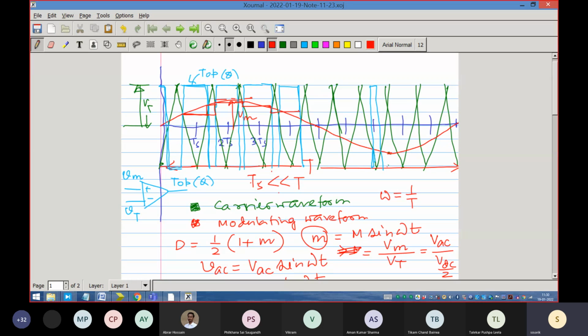But if there are enough samples, 4096 samples, there is hardly any variation from cycle to cycle, because you have good resolution of the angle. So there is no filter required. If you look at a drawing, it may look like it is varying a lot, because I have taken only 5 or 10 samples for 360 degree. You should think of it as 4096 samples per 360 degree. Then there is hardly any variation. Yes, sir, so there is no filter.